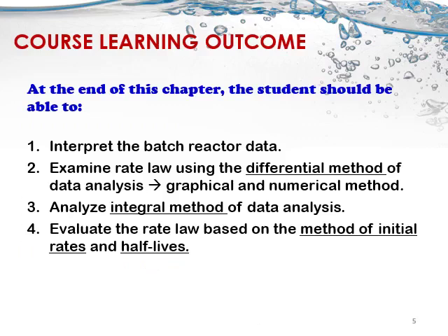There is one more reactor which is mentioned in your course outcome, that is PBR, packed bed reactor. For packed bed reactor, it's similar to PFR. The fundamental is PFR, except you have a bed of catalyst. Reaction only can happen when it's past this catalyst. Okay, when you have a bed of catalyst, it's called packed bed reactor.